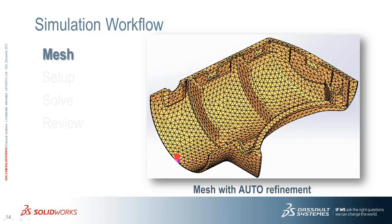In the conventional simulation process, one would design their product using a 3D CAD modeling software like SOLIDWORKS, and then export the geometry as a STEP file or an STL file into a meshing software, and then create a mesh to represent the geometry, and then export the meshing file into a solver where one would set up these kinds of simulations.